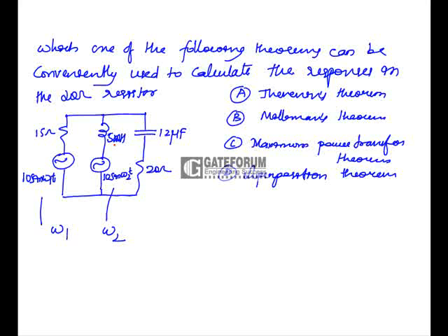Since we have energy storage elements, inductors and capacitors, these are frequency sensitive. When frequency sensitive elements are connected with sources of different frequencies, we have to use the superposition theorem. Why superposition theorem? Because we take only one source at a time, whether it may be a current source or a voltage source. So these frequency sensitive elements will respond to only one frequency at a time when one source is acting alone.